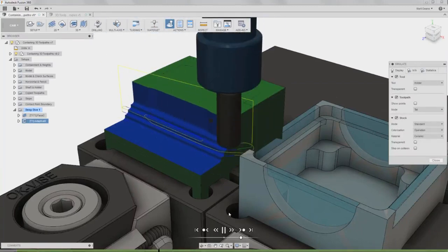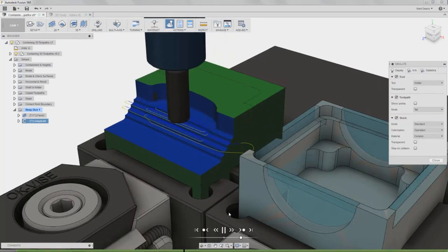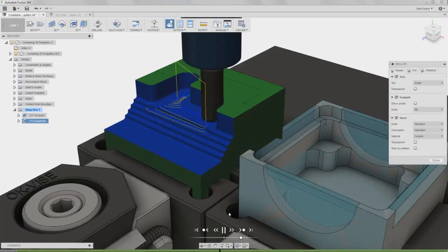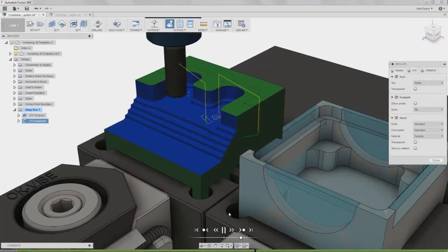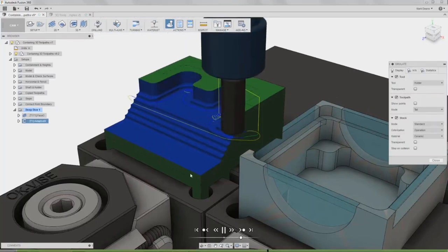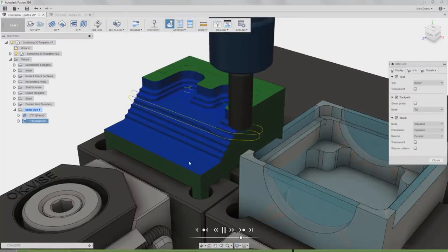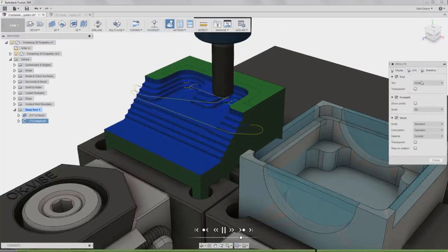And it'll do the whole operation in that kind of stair-step way where it'll cut all the things at that one Z height and then move up and cut all the things at the next Z height, move up, move up, move up, and so on. While this is going, we can see it kind of missed a little chunk down here, but that's because that was the maximum roughing step down.